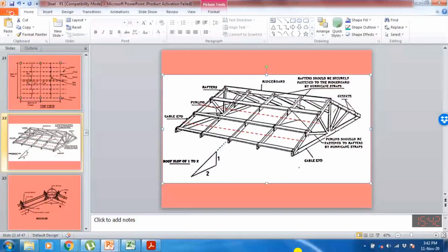So we need to multiply this total force with the number of the purlin, because this force is acting at each point where the sag rod is connected in the purlin. So actually we are using three sag rods, 1, 2 and 3. The sag rod is the rod which is used between two purlins. So force in one sag rod is taken from the chart. So how many sag rods we are having on the one side?